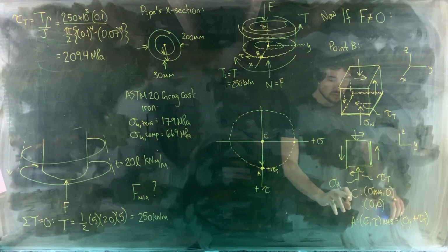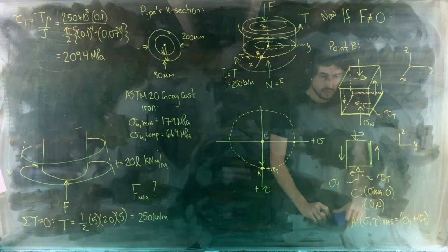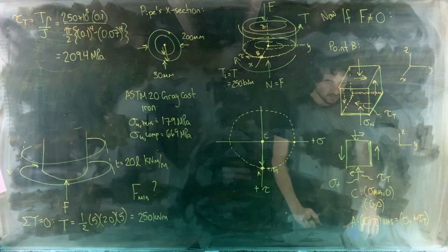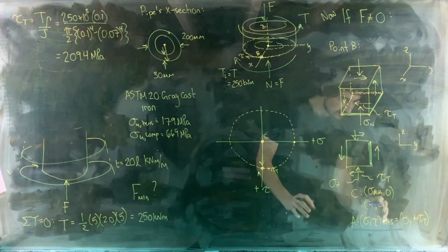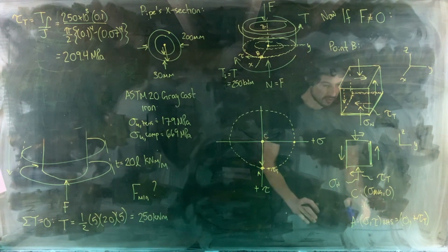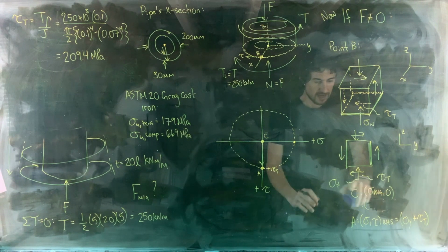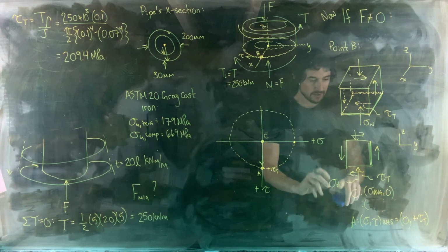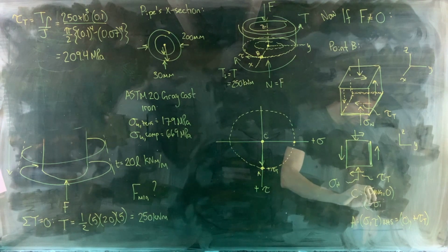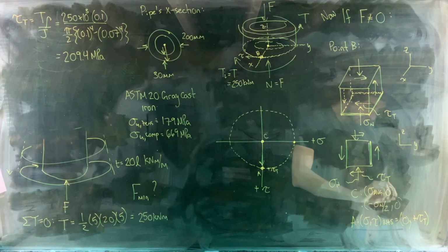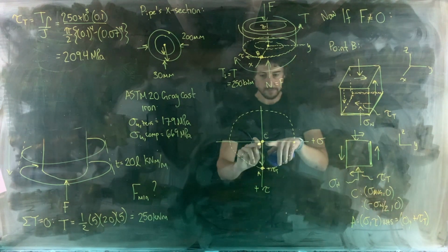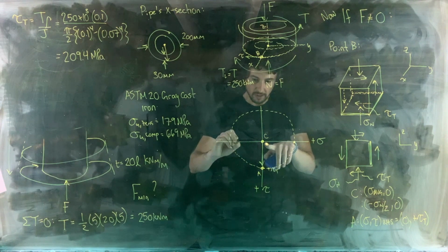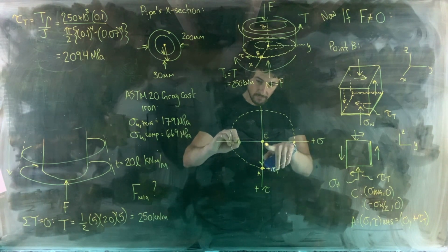What happens now to point C and point A? Point A in this case stays exactly the same, because the stress state on the element's right-hand side hasn't changed. But now point C has changed. The average normal stress now is negative sigma n divided by 2, comma 0. So the location of the center of the circle moves from here to somewhere over here.